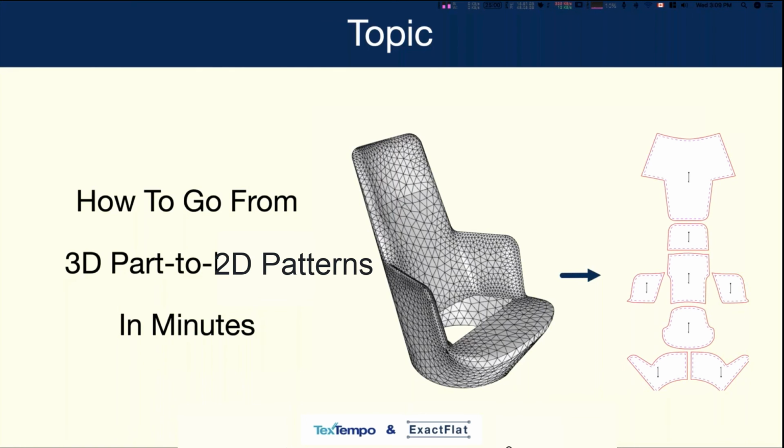So the flattener simply flattens the 3D mesh that's given to it. So it's your responsibility to split up that mesh into however many pattern pieces you require. So if through your normal processes you normally create your shoes as two pieces of material, one for the left and right hand side of a foot, then you would split your part in half according to where you normally would have your seam line. That's obviously going to create only two pattern pieces, and they may be fairly strained, but that might be acceptable depending on the material that you're working with.